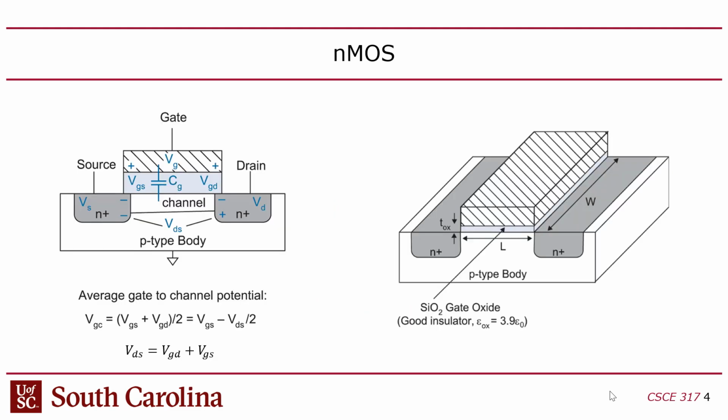Okay, so this is another picture of it. So this is an NMOS. You've got the gate, you've got the body or the substrate, and then the two diffusion areas. And then directly underneath the gate, you have glass, which is insulator, and then below that glass, you have the channel. So I mentioned that there is a capacitor formed here between the gate, which is that polysilicon.